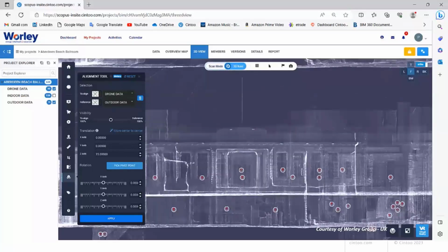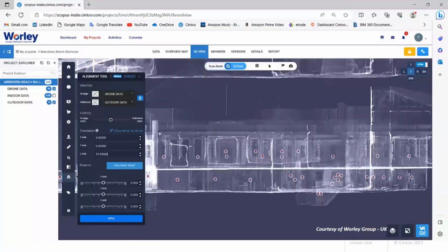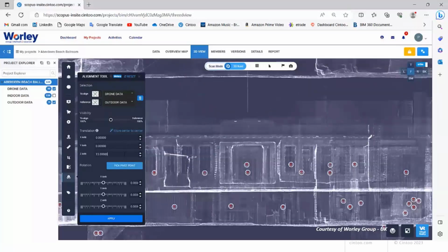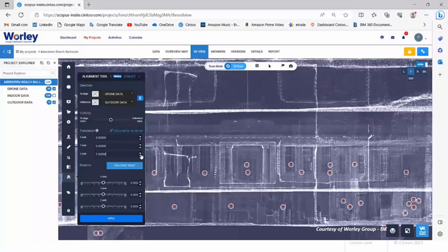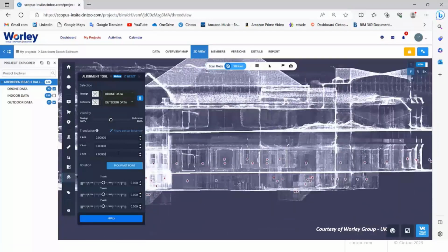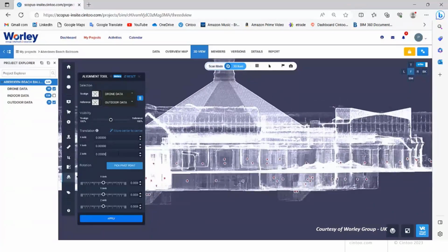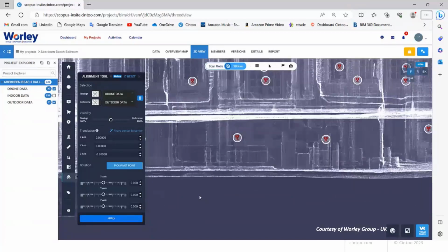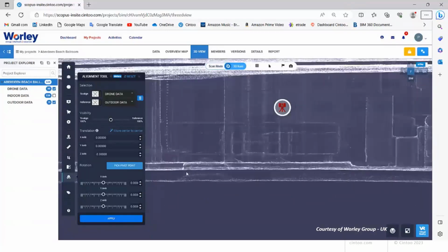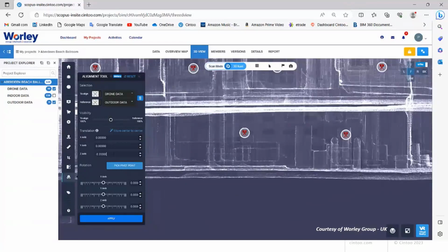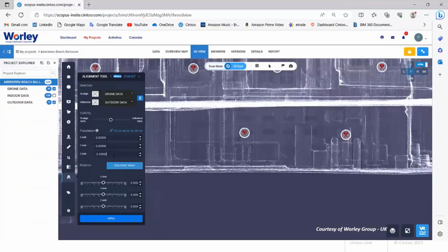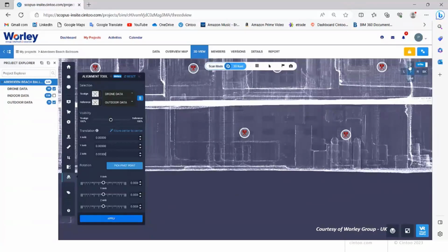And if you zoom in, here I'm using the mouse wheel to move the data set, but you can also type any value. Also, when you use the mouse wheel, you can use Control, Alt, or Shift to have smaller increments. So when you get closer to where you want to go, you will press Alt, and then you will press Shift, and you will zoom in to make sure that the two data sets are being aligned. So Shift plus mouse wheel here will give you a very good sense.